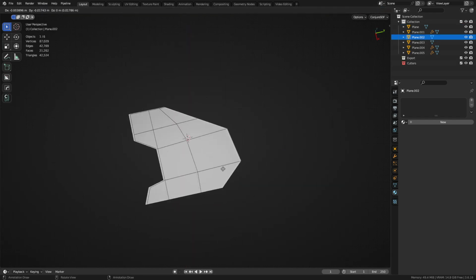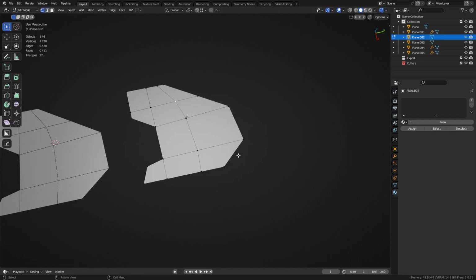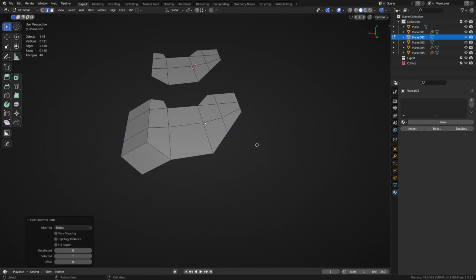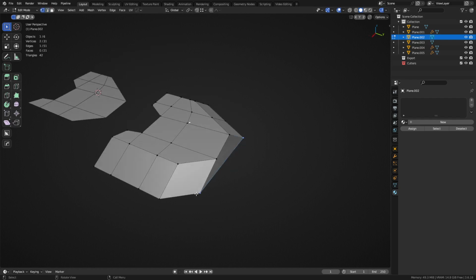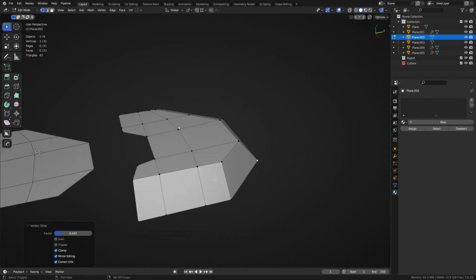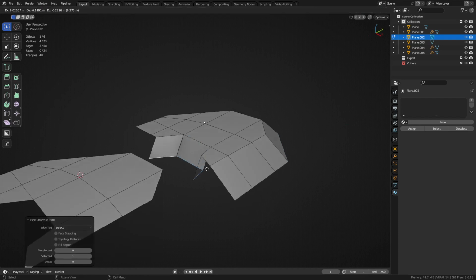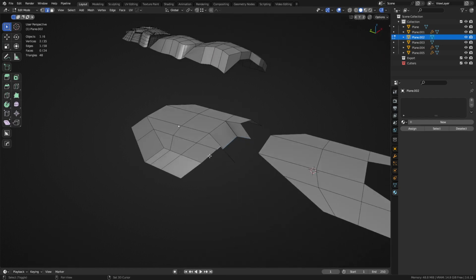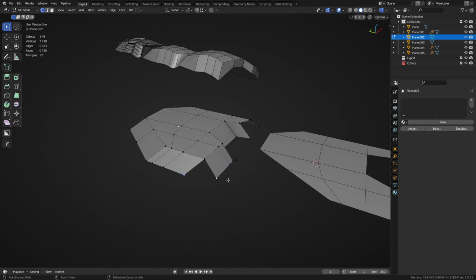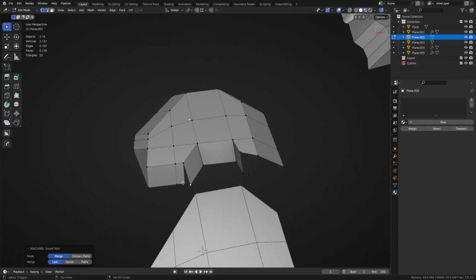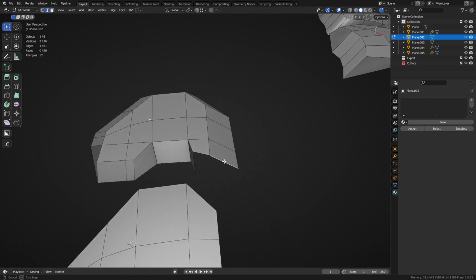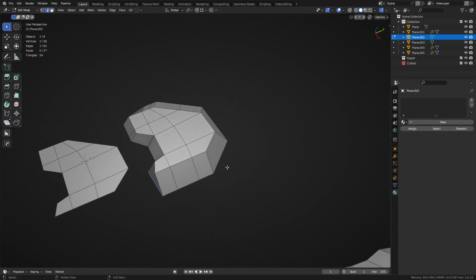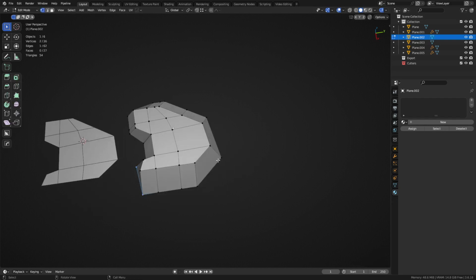All right. Now, you guys are going to probably go too far, too quick on this. So let me show you what you probably will do and you shouldn't do. So you start making these kinds of shapes, start working them out. Doing stuff like this, just extruding edges, right? And merging some of these vertices back to the other vertex and merge at last. Okay. And then you probably start adding all of your holding edges, which we're not going to do, but that's probably what would happen.